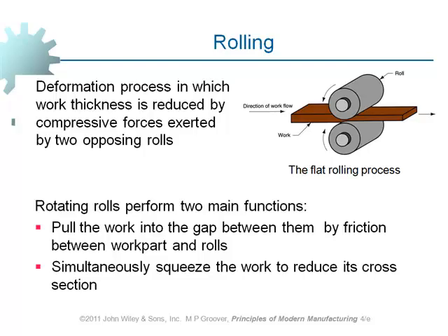And what explains this? Because material has been subjected to cold working. When a material is subjected to cold working, normally it becomes harder and stronger. Reason, it's been deformed. And when a material is deformed, it means that there are always a number of dislocations present in engineering materials.